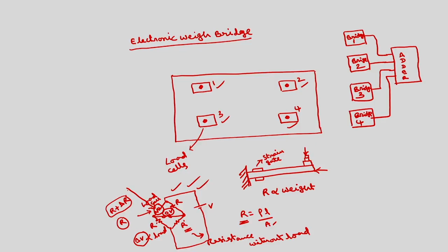Still this voltage, this delta V, will be very small. So, that small voltage we cannot directly apply to the microprocessor. This voltage of the adder can be applied to the amplifier. So, I am connecting here, this is A point, this is A point, there is a link between these two. So, you have to connect to an amplifier.